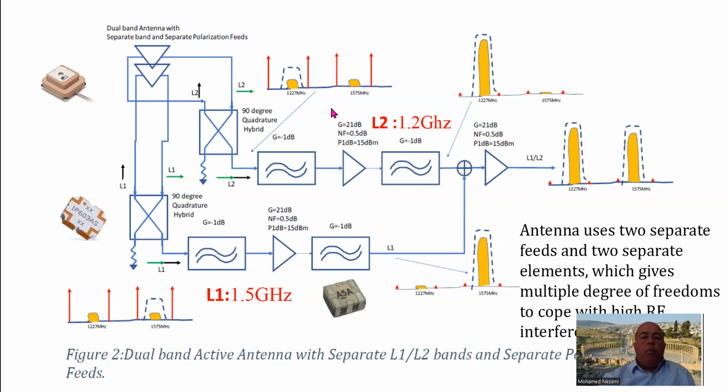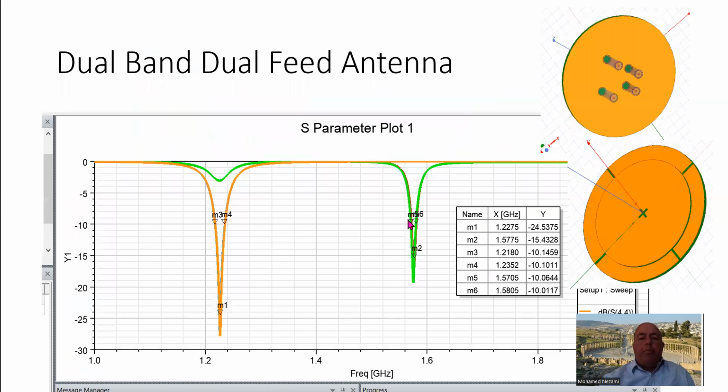Hopefully, when we do that, if you see graphically here what happens to the interference, it gets eliminated because we're amplifying and filtering separately, so we have more control over the bandwidth to zone in on the band of the desired signal more narrowly, so that we reject the out of band.